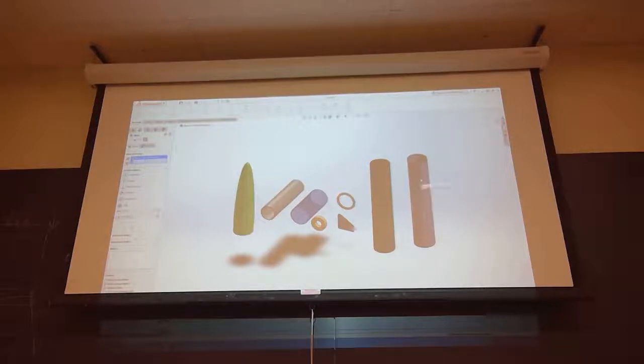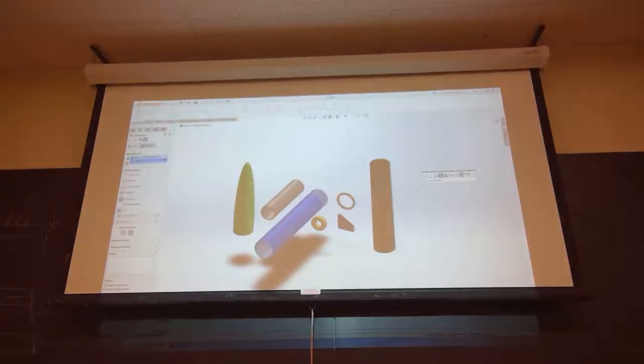So then you can just go ahead and select the outside or the inside tube of the main tube, and wow, nice. It automatically picked a constraint for me that it thought would be best suited. Okay, so it actually should have done this for all of you if you picked it right. It should have automatically gone to concentric. But I can do other things such as, I want them to be parallel, perpendicular, tangent. But again, in this case, we want them to be concentric, okay? So we just hit concentric and we hit OK.